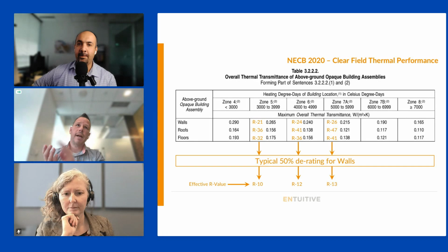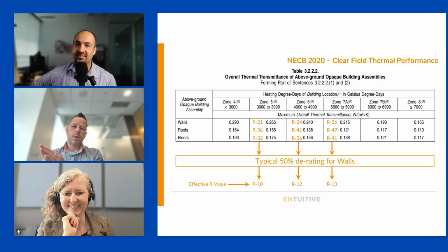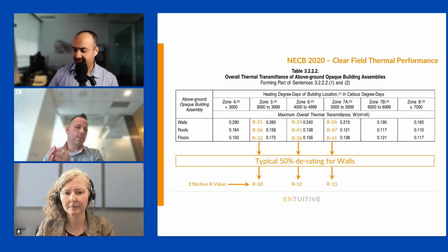The other cruel reality of thermal bridging is that it gets worse when you add more insulation. So when you get to that level of saying, well, we'll just add another inch of insulation, you're not ever going to get anywhere close to your return on investment for that. Focus on the details. Focus on thermal bridging.